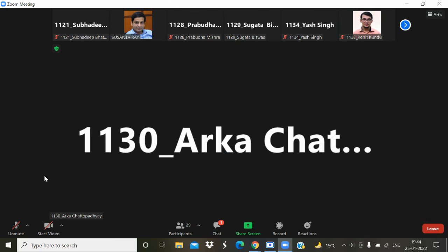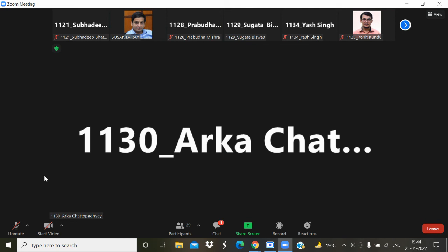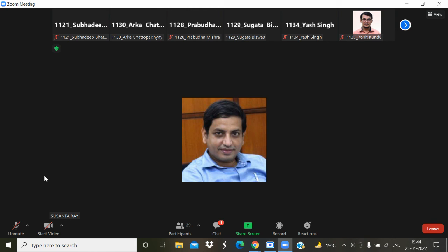Sir, for a 120 kilowatt machine and 1000 RPM, my D value is coming as 390 millimeter and L is 408 millimeter. It's okay. You just see one thing, that your L and D values should not deviate too much. Like just now his value is 300 and 280, it's acceptable. Sir, my values are deviating by 18. It's okay, that should come near. A 50 or 60 millimeter difference is acceptable.